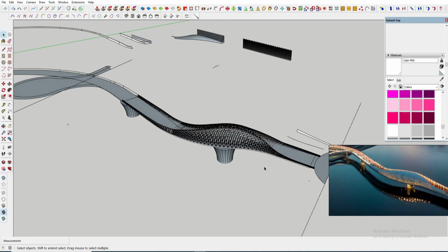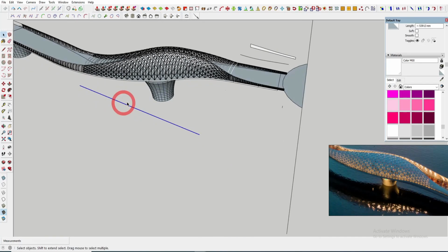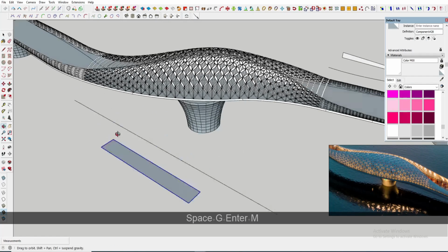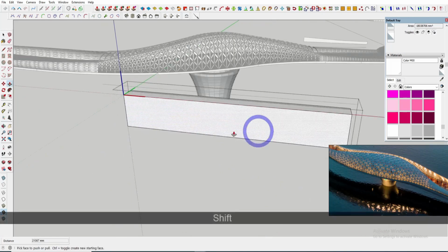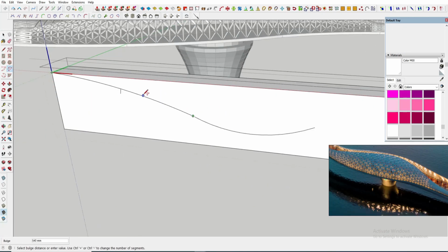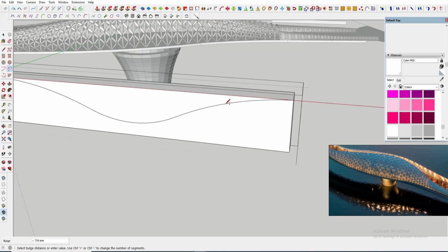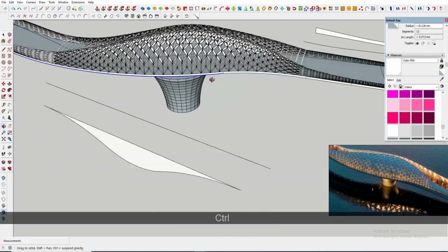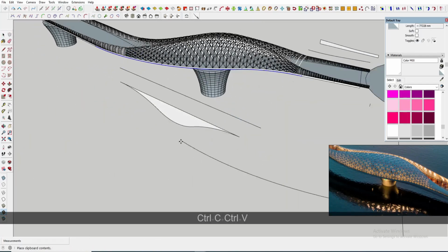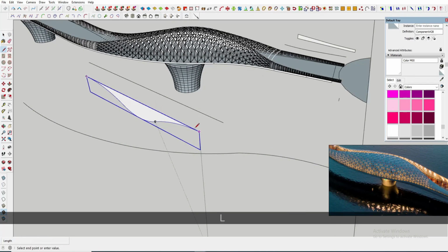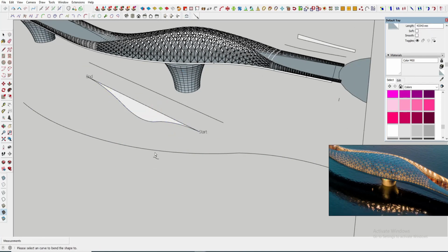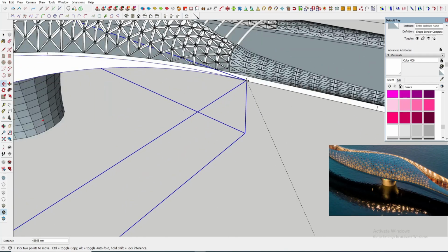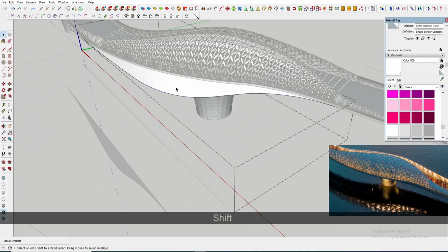Now we are going to make the bottom smooth edge. Here also I'm going to use the same process. I'm making the elevation profile first. I'm going to bend the whole surface by using the Shape Bender tool. I'm taking the reference from the edge. I'm bending this whole surface all along the existing edge. Then I'm using Joint Push Pull to give a little depth.